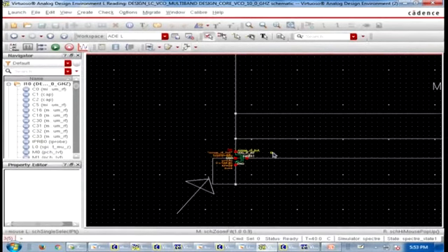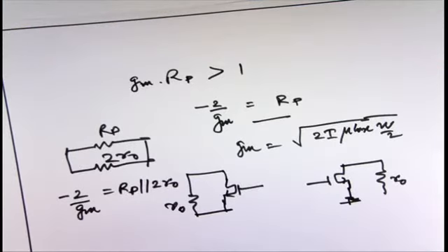So they will give some kind of script and you have to run that. For example, here I am using around 0.2 nanohenry, that is 200 picohenry, as the inductance value, and the quality factor is around 35, but only for that particular point of operation. Okay? So again the problem is twofold.